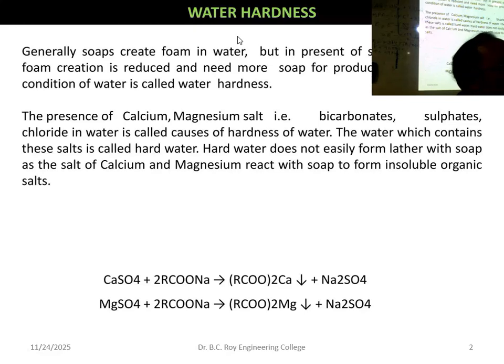If you use a bucket over a long time, there also you can find that. In hard water, you can find scaling. The scale is cracked in different places, and cold water seeps into the crack. On the metal surface, both cold and hot are present, so it creates a lot of stress and the boiler will crack. And the boiler is a very costly alloy material, so if it cracks or is damaged, there will be a lot of loss to the company.